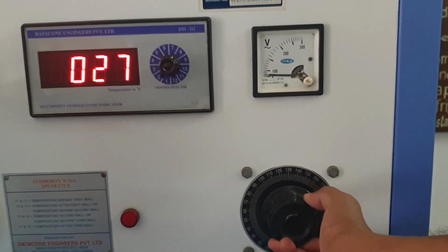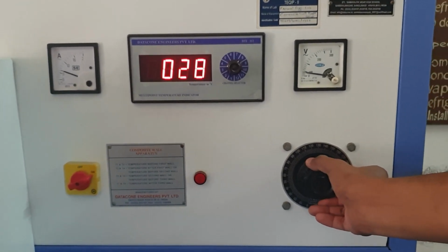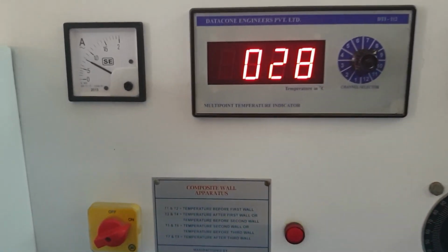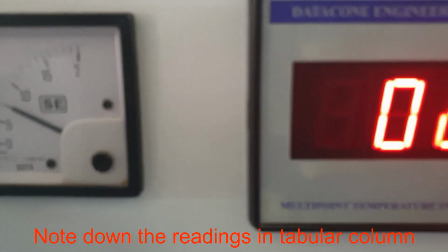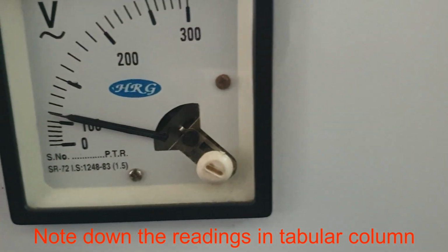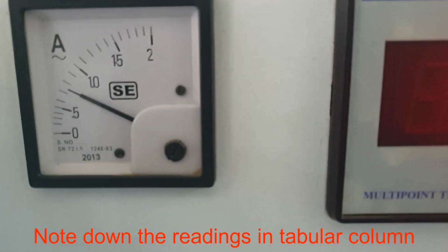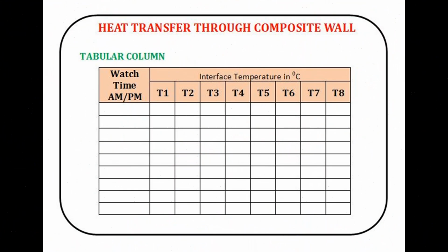Now we will start giving some heat input. The voltage is being increased to about 100-110 volts, and correspondingly the ampere will be increasing, and VI cos theta will give the electrical energy input, and we assume that all the electric energy is converted to heat energy. These values are noted down along with these temperatures. We need to wait for steady state to be achieved, so that the temperature at a particular point will not vary with time. So at 10 to 15 minute intervals, the temperatures from T1 to T8 will be noted in this tabular column.